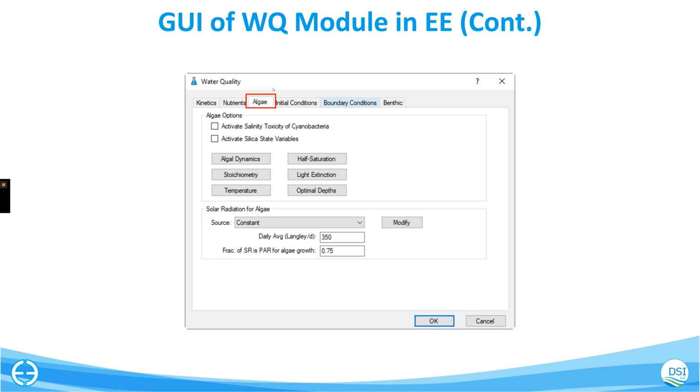You'll find that as you get into these water quality models, it is super critical to get your temperature sensitivity right. We've got tools to help identify, or at least visualize, the inputs you're putting into the model, to make sure they make sense when you're parameterizing and calibrating.